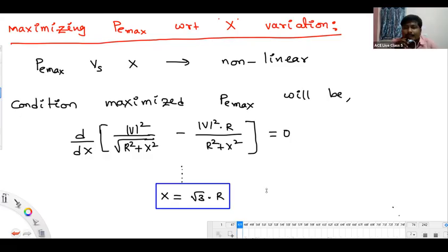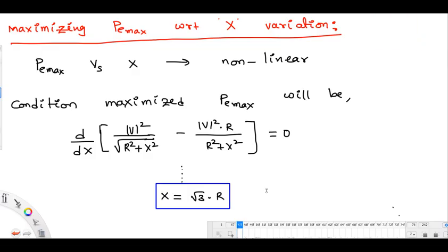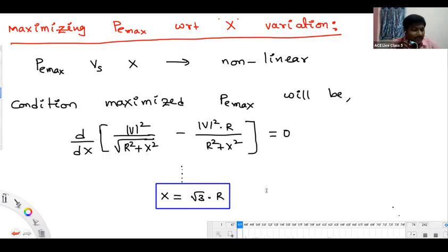Sir, if the question gives positive sequence, negative sequence, and zero sequence impedance, and they indirectly say to find the fault, find the voltage in the healthy phase where the other two phases are faulty, can we consider it a double line fault? It may be double line or double line to ground also.